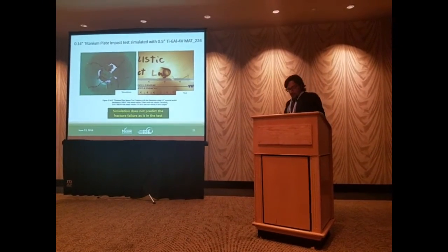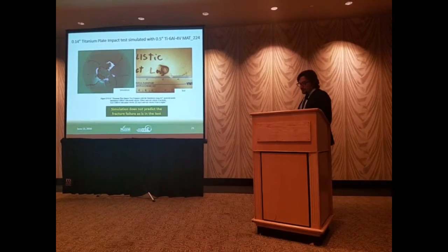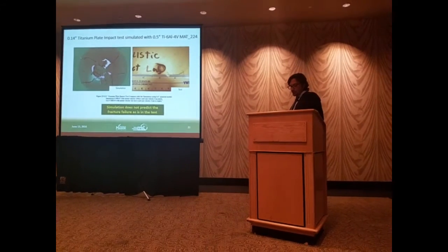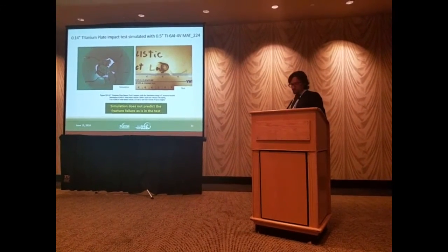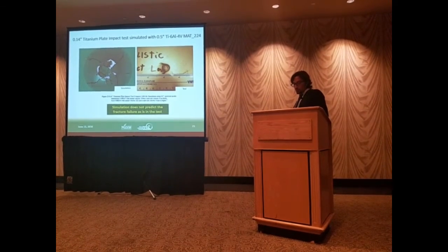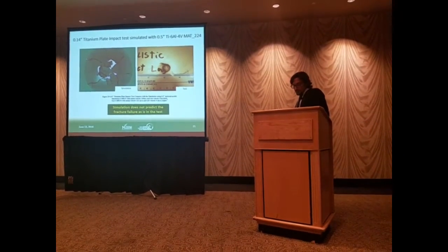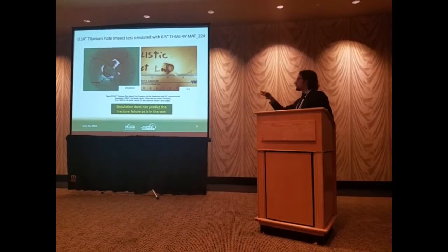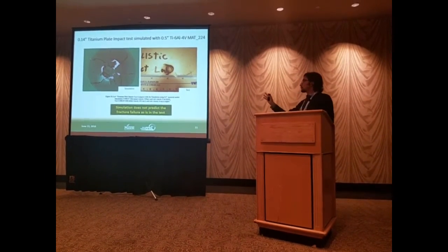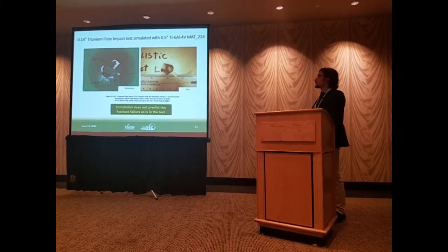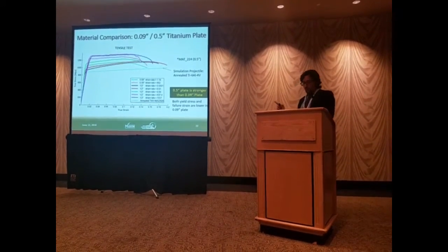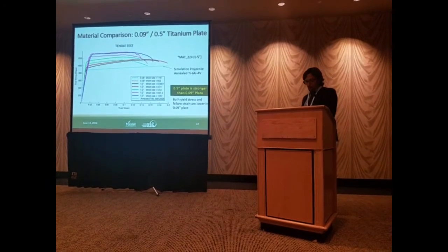Okay. You can see the picture on the left shows the failure mode for the simulation with the highest containment velocity without plug, because we wanted to match that kind of test, and we completely miss the failure mode. So simulation does not predict the fracture failure as in the test. So we move on to the last plate.